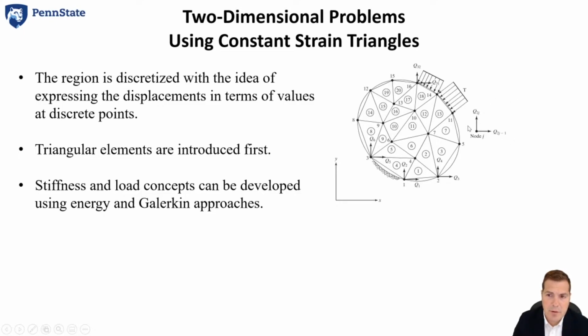Okay, now you got to remember Q is what? Q is the displacement vector. And so what we're going to do here is store XY data in a one-dimensional array. How do you do that? Well, you do that by the correct counting system. Okay, let me say that again. You're storing two-dimensional data, XY displacements, in a one-dimensional array.